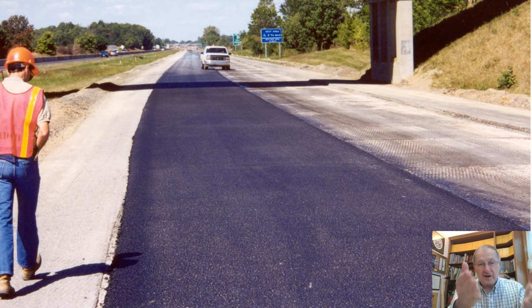And clearly they're breaking aggregate. And so the thought was, hey, hold on, we can't compact this new mix. It is not compactable. So what we did is said, okay, well, let's try and see if we can figure out how to compact this. And one of the things that we decided to do is to slow down the rollers.